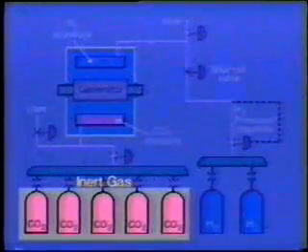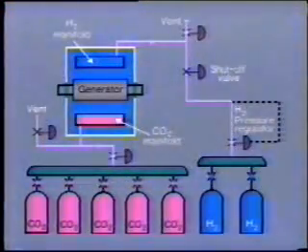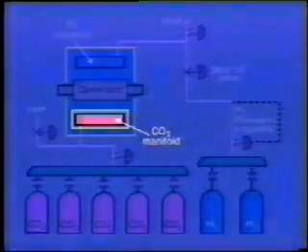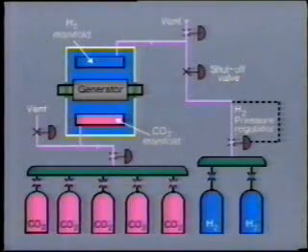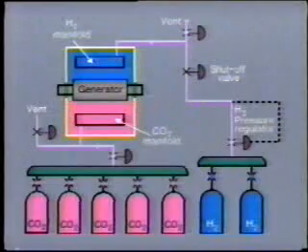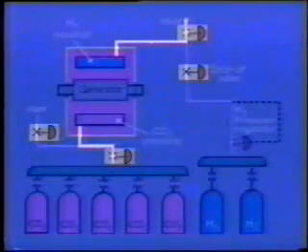CO2 is a completely inert gas that is non-flammable and non-explosive. The CO2 gas is admitted under pressure through a manifold at the bottom of the generator casing. This gas is much heavier than hydrogen. As it fills the generator casing from the bottom upwards, it slowly rises and pushes the hydrogen out of the top manifold. The correct valve arrangement must be selected by the operator so as to allow this top manifold to discharge to atmosphere instead of receiving hydrogen from the bottles.